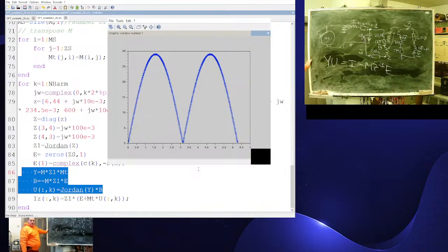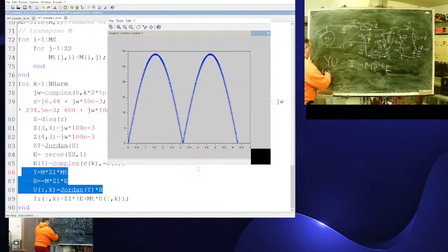It's derived from the nodal potential technique, where this matrix is called the nodal admittance matrix. It's M, inverse, M transposed. That's why I needed M transposed and inversion of the resistance matrix. This one will give me nodal voltages.